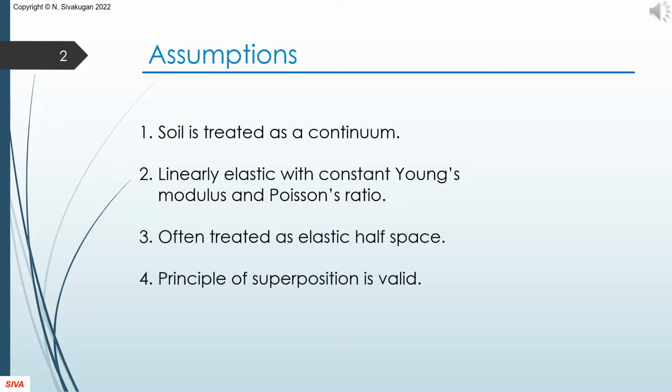These are the assumptions we make for developing expressions for computing the vertical stress increase at a point. We treat soil as a linear elastic continuum, with a constant Young's modulus and Poisson's ratio. Hence, we can apply the principle of superposition.